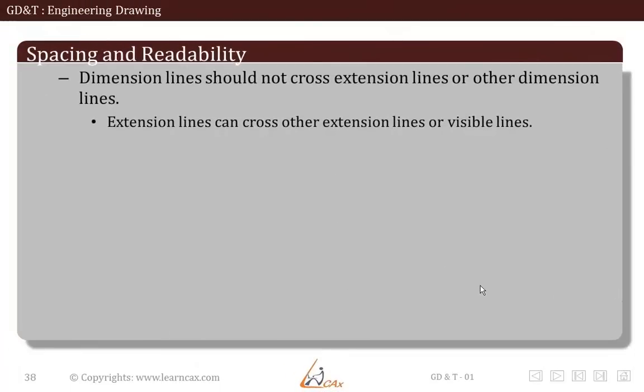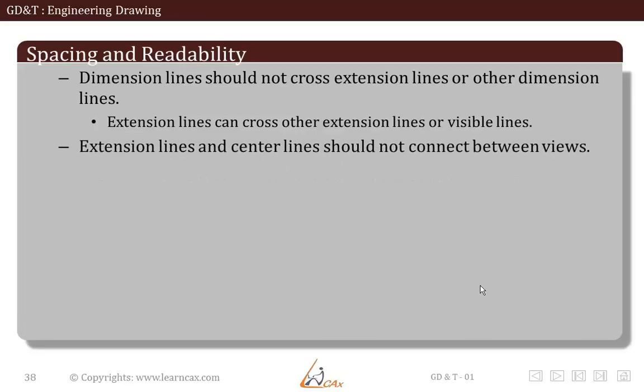Dimension lines should not cross extension lines or other dimension lines, but extension lines can cross other extension lines or visible lines. Extension lines and center lines should not connect between views.